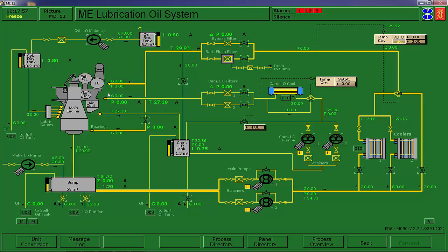the fuel that is used to lubricate the pump plunger and barrel can drip onto the camshaft follower and then gets incorporated into the lube oil that is lubricating both the camshaft lobe and that follower. So in other words, you get fuel dilution. And this increases steadily over time because those fuel pumps, as this engine is running, are always dripping this fuel into the lube oil. So Burmeister Wain has a separate system for camshaft lube oil.